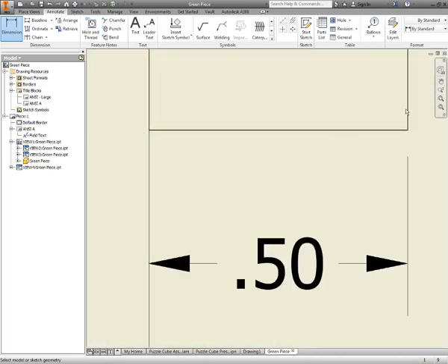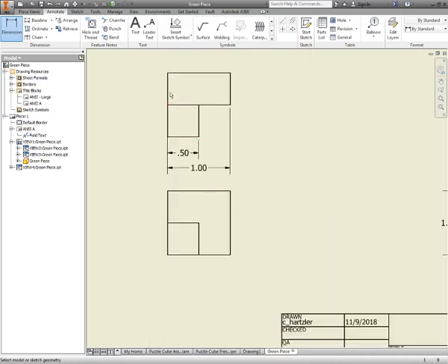I tell you guys, don't touch your part. This one over here, that's a good gap right there. Should be a 1/16 of an inch. Over here, I'm touching. That's because I clicked way up here, and it's actually getting a 1/16 of an inch away from this line. So I'm going to press Escape, right click, delete, and then I'm going to click on dimension. I'm going to redo that.